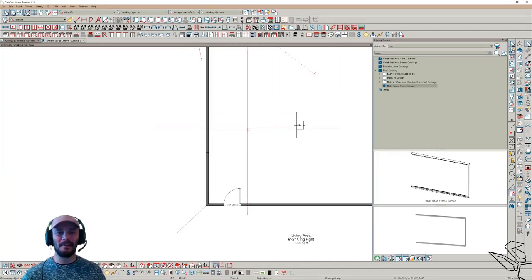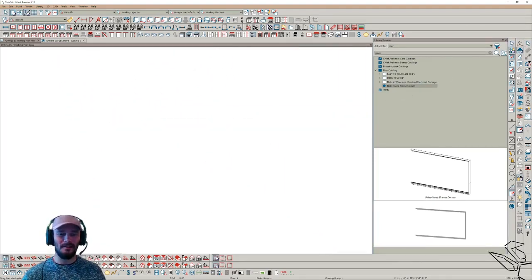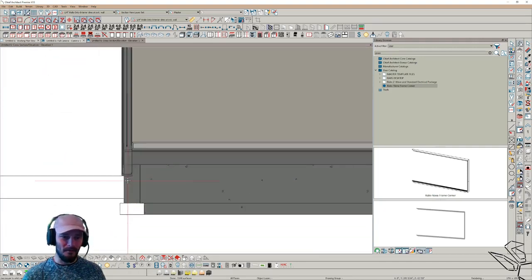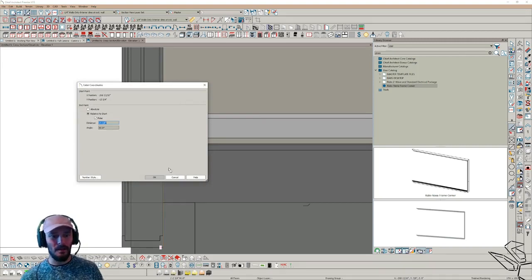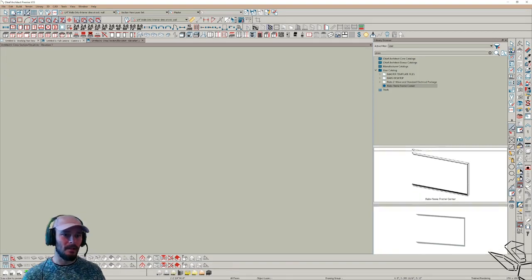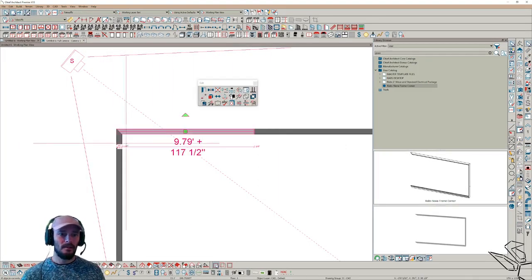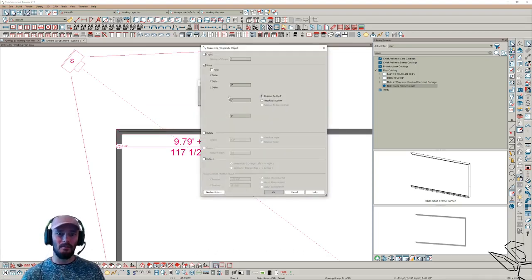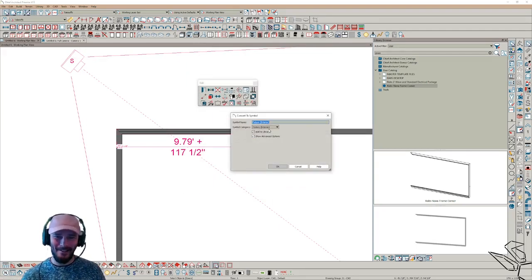I'm going to fix this real quick. It's going to take 2 seconds. I just had to think about it for a second. So I'm going to pull elevation. I'm going to snap it through here. And this is what I'm looking for: what is the bottom of our P solid here? Well, it's here, and then there's the bottom of the cab. And then I can delete this now. Select all this. Move this full assembly. 14 and 5/8.